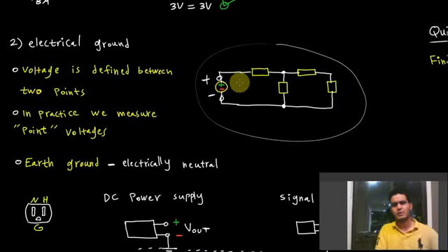In reality though, we'd like to be able to just use one point, one probe, and probe different places in the circuit, in a more complicated circuit, for example. Now what we do here is we use a symbol called ground, and we usually go to the negative side of the supply voltage, and we ground that terminal or that point in the circuit.